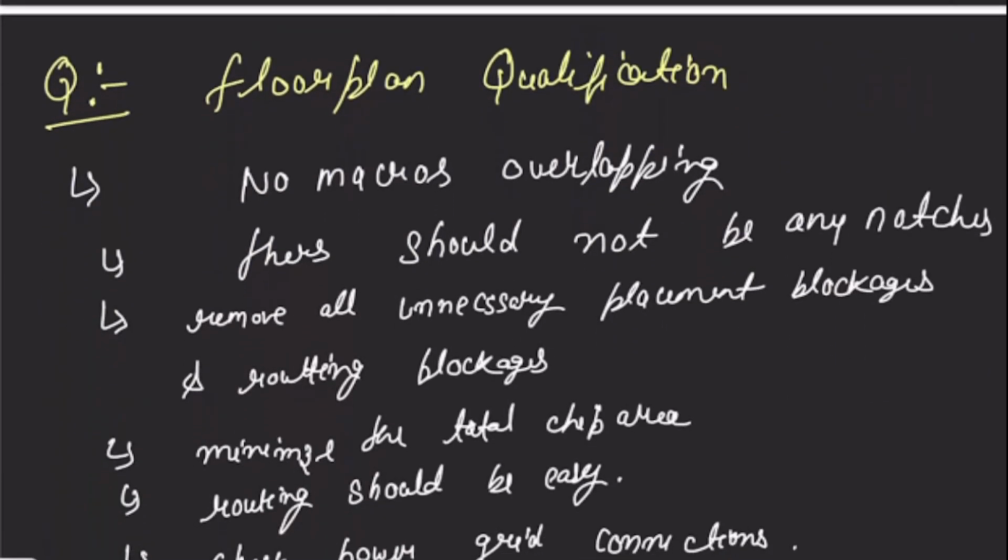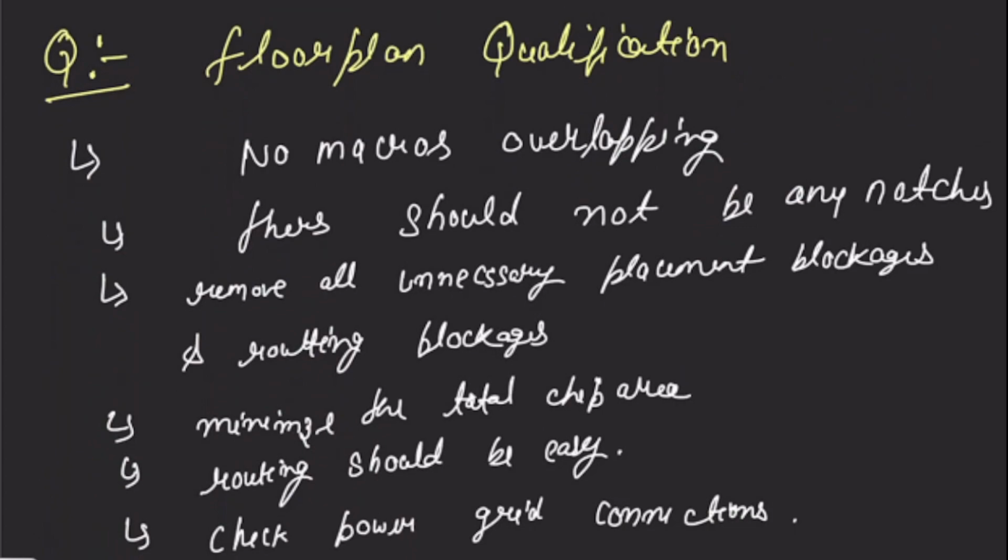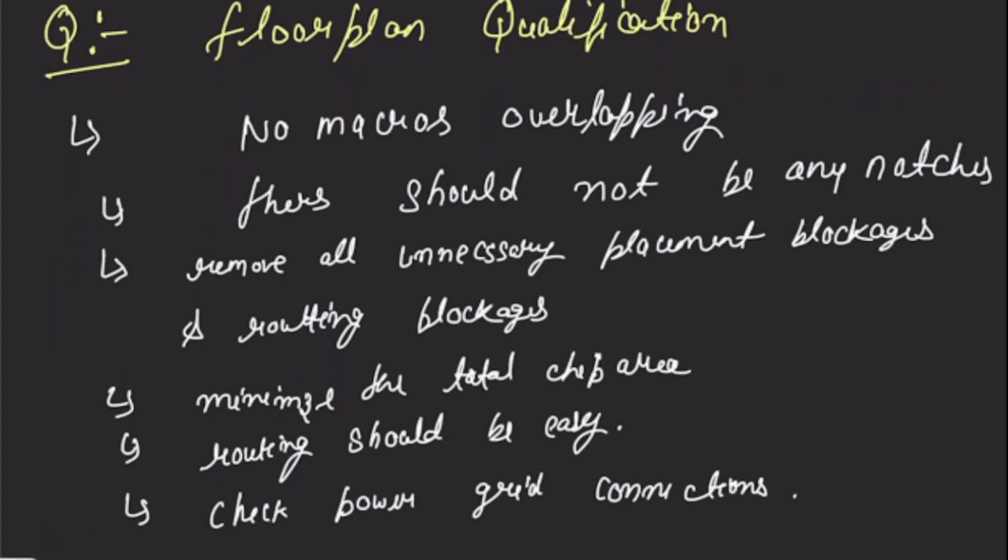Next question: what do we need to qualify for the floor plan? What is floor plan qualification? No macros should be overlapping. There should not be any notches.